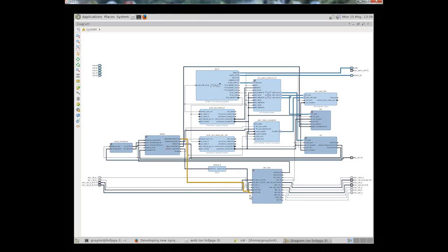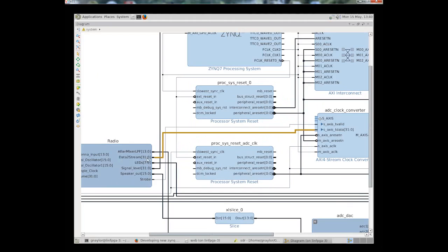We can look, for example, on the oscilloscope at the signal that's going on here. But also we put in a facility to stream data digitally back into the ARM, so that was this line here. If we zoom in, we took data from this radio block and streamed it into this block here, and we clocked it with this value here, that each time the value was updated we sent a 1 clock cycle pulse here.